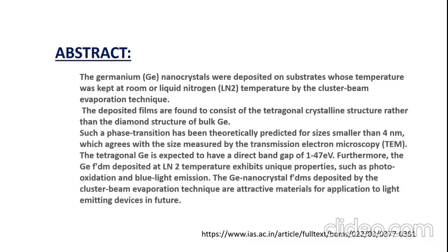The next one is a small abstract that I have taken from a research paper, which describes the cluster beam evaporation technique for producing germanium nanocrystals when they are deposited on the substrate, by controlling the temperature at room temperature or liquid nitrogen temperature. This entire preparation of the nanocrystal is based on cluster beam evaporation.